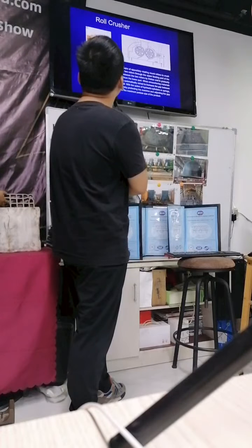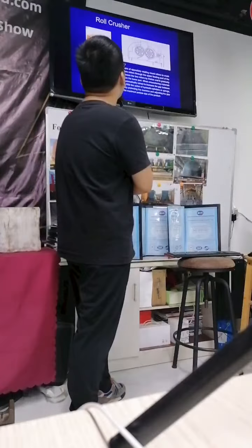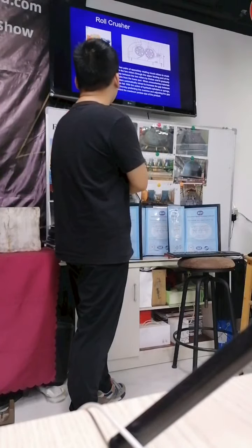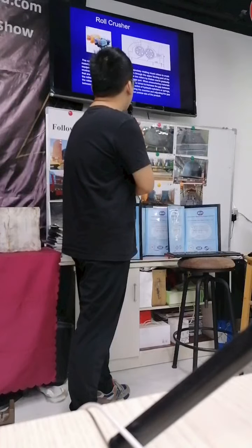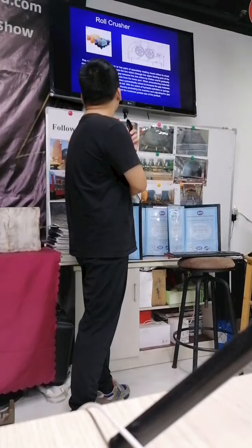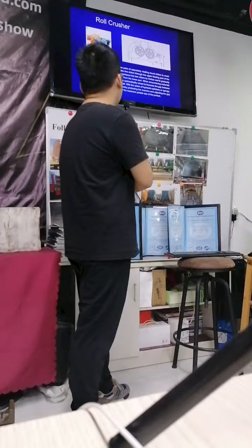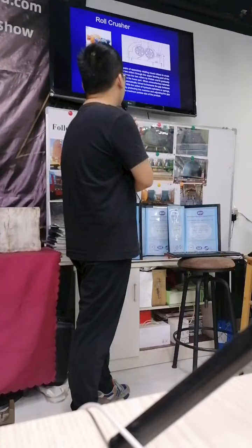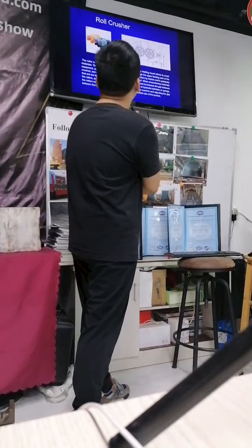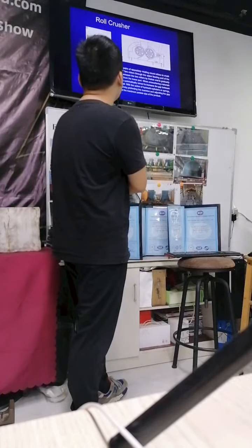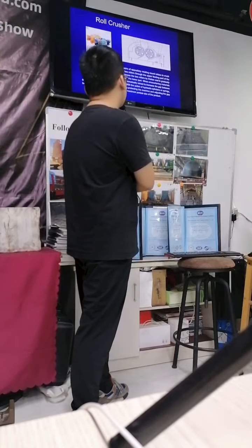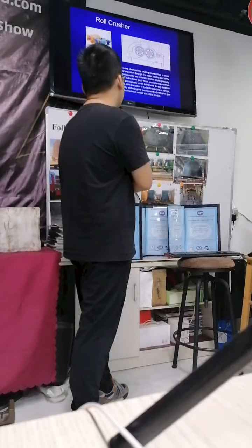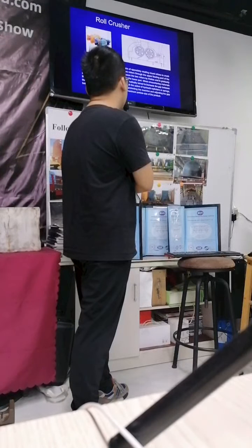The materials fall between the two rolls through the upper feeding port of the equipment, are drawn into the gap between the two rolls by friction and gradually crushed, and the finished material leaks from the discharge port. When materials that are too hard to be broken get in, the rollers automatically increase the gap between the rollers with the action of the hydraulic